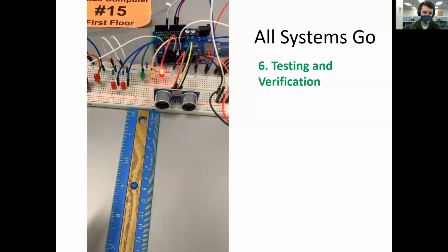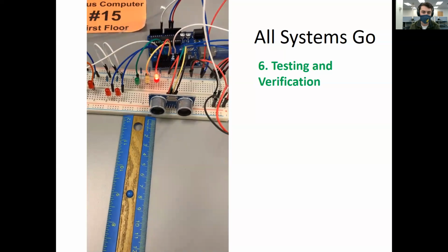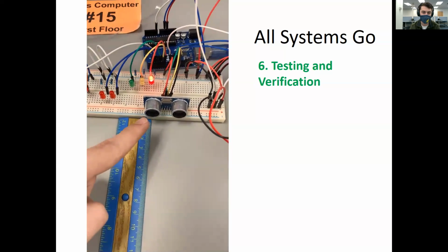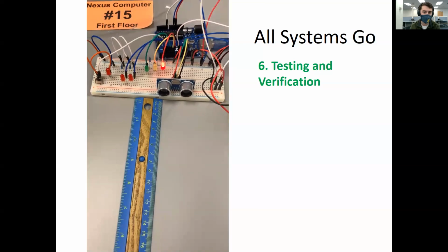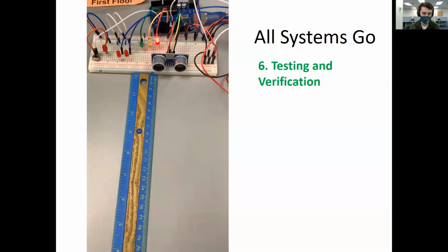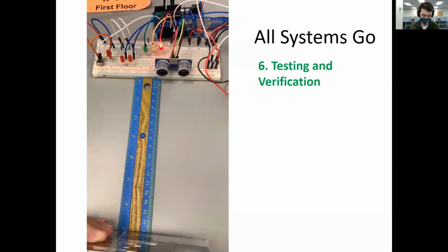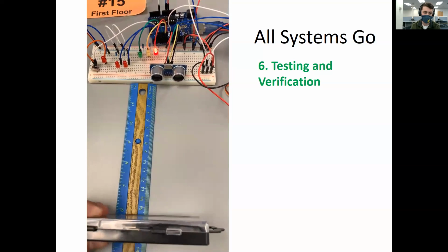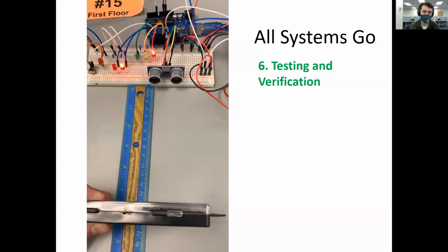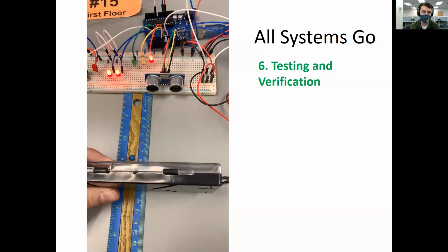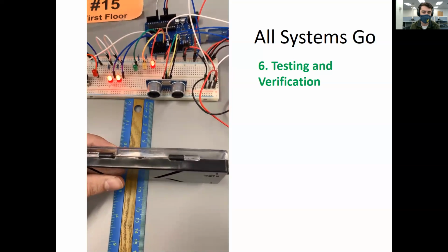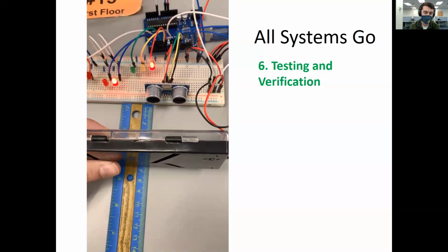Up next will be the low altitude system involving the ultrasonic sensor and the 2 red LEDs. So when you're far away, nothing is happening. You hit 15, one turns on. Moving up to 10, you'll have both LEDs turn on, and at 5, they'll start flashing.